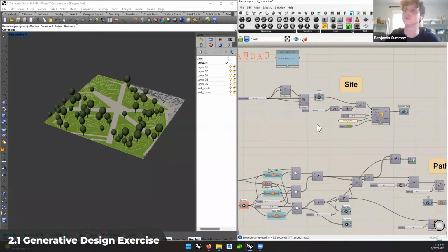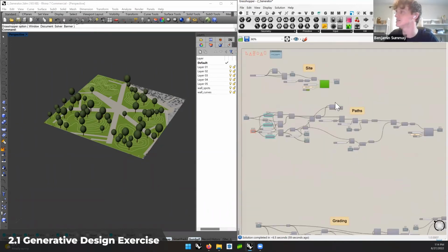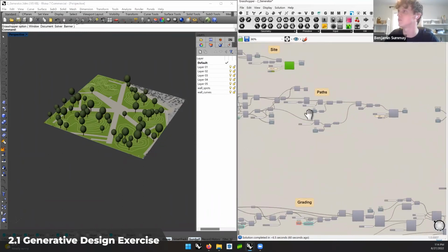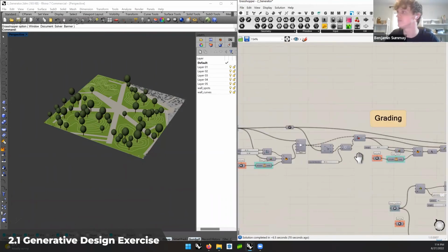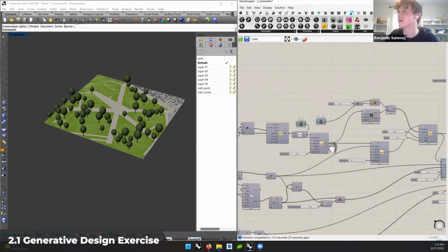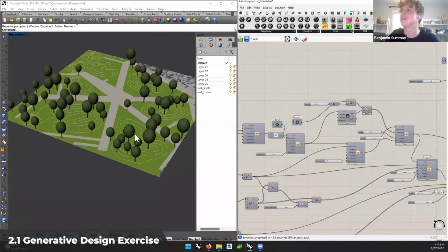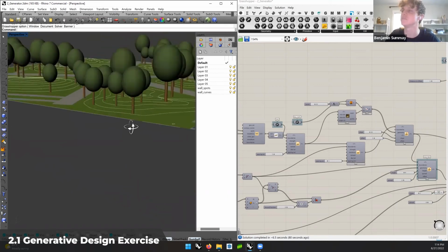But in this case, we're just using a general rectangle for the site, and we're using a combination of different tools being generated in Topo Kit, such as the Create Areas component, which feeds over to different areas, and Paving Kit, so that we get our paving pattern being mixed in with the whole site. And then we're also using the areas and the topographic tools of Topo Kit to regrade the site using randomized points and paths and things like that, so that we can create these randomized mounds in the green areas of this city park type feel.